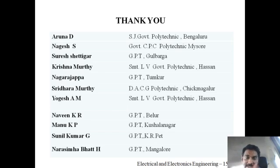By observing the characteristics, we can conclude the DC series motor is used wherever high starting torque is required, and a wide range of speed variations can be achieved by the DC series motor, and the DC series motor should not be started at no load. If we start it, it will damage the motor. It will run at very high speed.